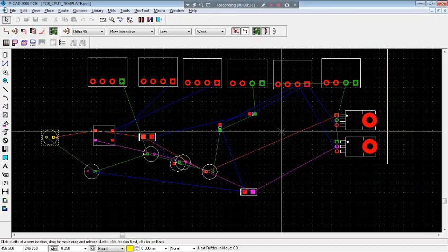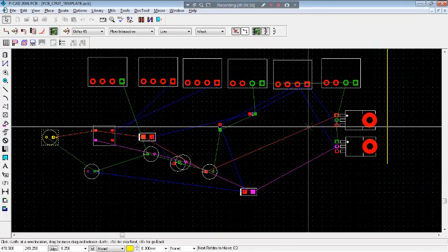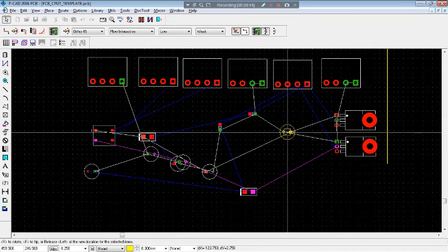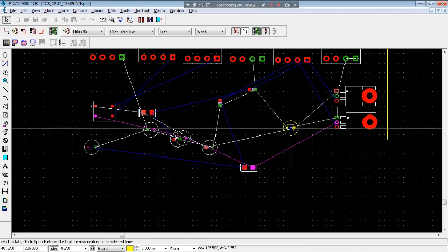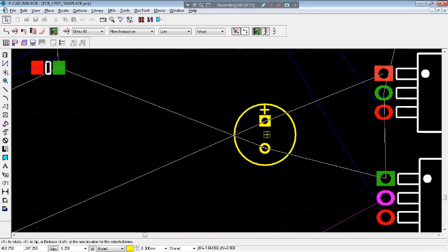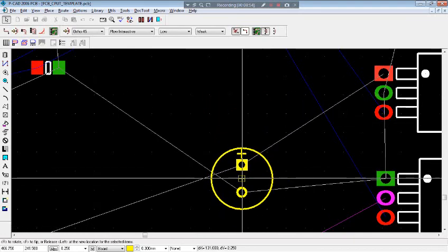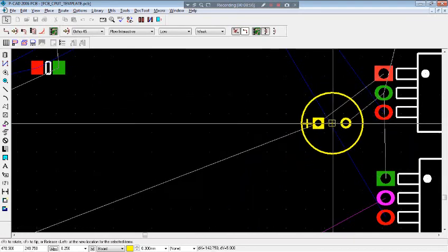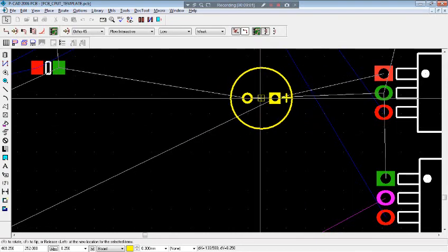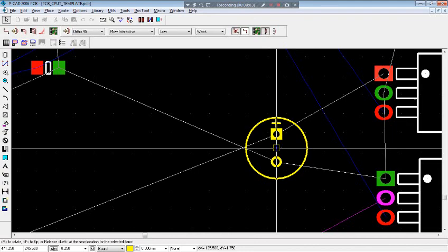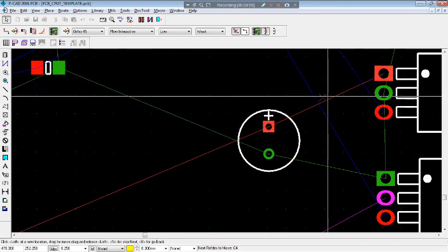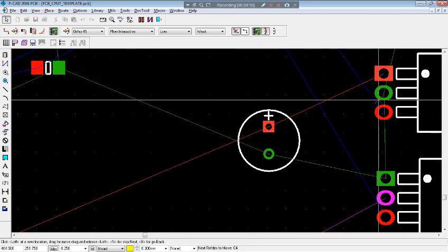Say OK. Now, this is our voltage regulators. Let's place the first capacitor here. I'm still holding the component. If I hold down control, I roll the mouse and zoom in, get a better look at that. Rotate it. Now, still crossing quite a bit. Move it on, rotate it. We start off by having it as close to the regulators as possible because that's what our schematic was set to. So let's try to not have it crossing. That looks the neatest for now. Don't worry about this because we're still going to sort that out. As you can see, there's less crossing here. Like that.